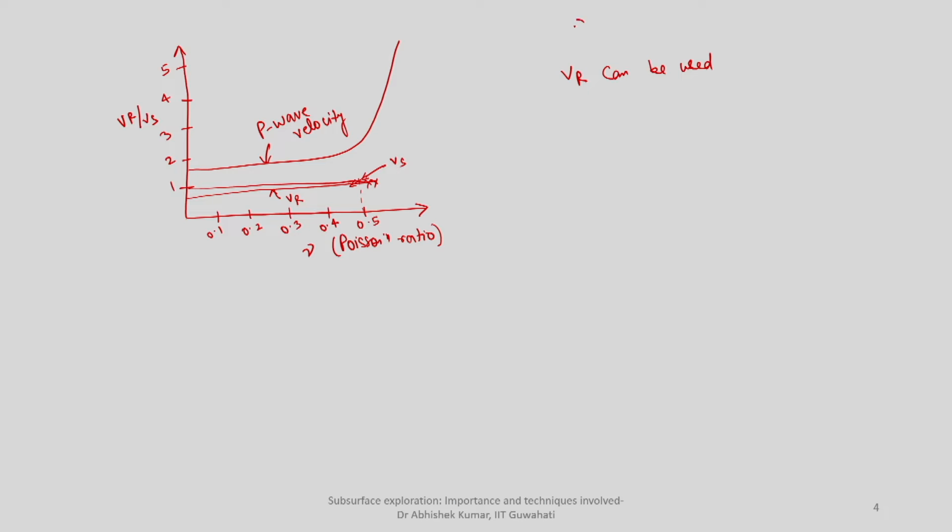So, when we go for the surface wave method, we are interested in finding the Vr value. Based on your field record you will determine your Rayleigh wave velocity. It can be further used to estimate shear wave velocity. Again, based on your shear wave velocity you can classify your subsurface medium.